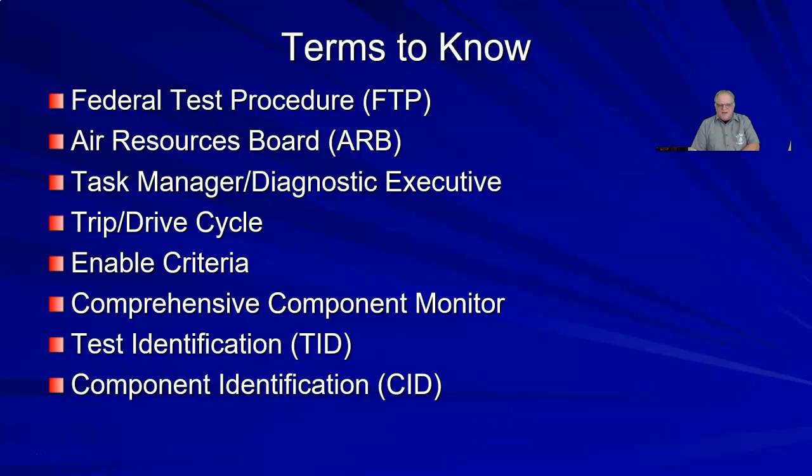The reason they do that is because people will drive around for 18 months, 19 months or more, however long it is between emission tests, with their check engine light on. They know that if the battery goes dead or if they disconnect the battery, it takes a day or two for the light to come back on. So they think that if the light's not on, they can go in and get an emission test and pass. But when you disconnect the battery and clear the codes, it also resets all the readiness monitors.